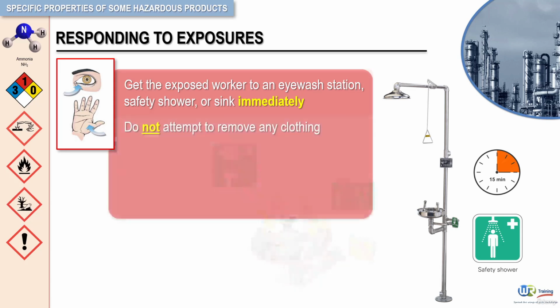Do not attempt to remove any clothing at this point. In many cases, the extreme cold temperature of anhydrous ammonia will freeze exposed clothing to the skin, and removing it can cause additional injury to the skin. Wait until contaminated clothing has been thawed before removing it.